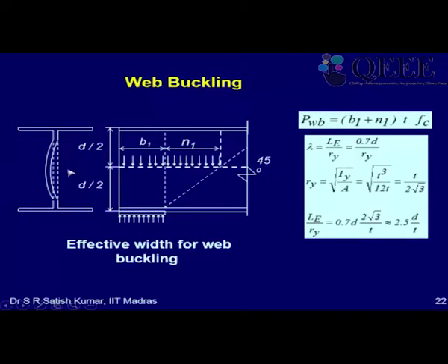So by the time you come to this section which is buckling at the mid height, you have B1 plus n1 as the width of the member and Tw as the thickness. So I have a plated cross section of this much width and thickness Tw, which will buckle obviously about its weak axis. So its weak axis is about the thickness axis. So it will buckle like this, right? And it is going to buckle between the flanges with this end and this end as if it is fixed.